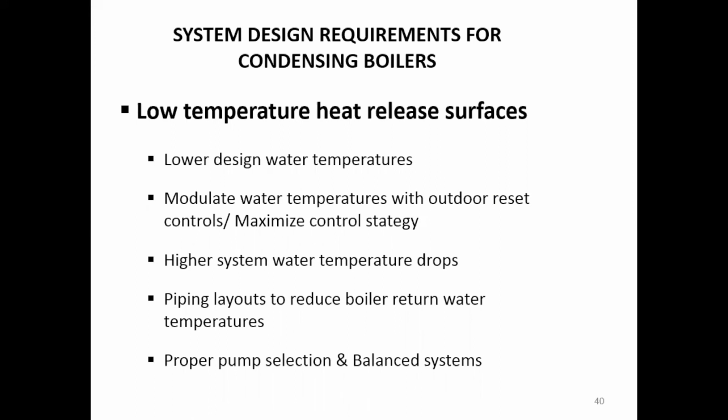It's about how I modulate the water temperatures with outdoor reset control. And to me, I want to maximize the strategy. If I have a minimum water temperature, let's see what I can do to stay at that minimum water temperature for the longest time, not for a short period, maybe in the shoulder seasons. If I can, let's look at a higher water temperature drop. Let's design for greater than a 20-degree drop, a 30, a 35, maybe a 40. If I can, let's pipe around that. Let's reuse the water a couple times in a brand new situation. Let's build motorized mixing valves into the project to get that water temperature down. And again, from a design and from a setup standpoint, pumping and balancing are important to driving it from a